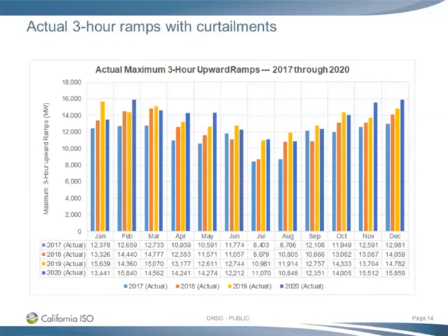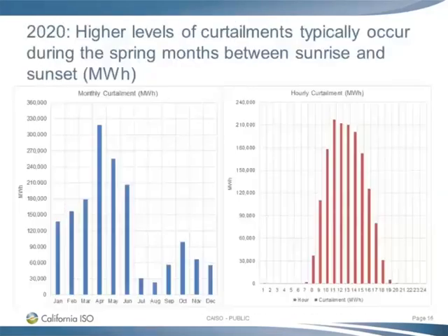Now, if you look at slide 16, we keep track of all the curtailments. So we have system, economic. We track this by every RTD interval, right? How much wind and solar we curtailed. And then we go back and look at this, and if you look at what we actually curtailed in 2020 by month, you can see April we curtailed quite a bit, May quite a bit.